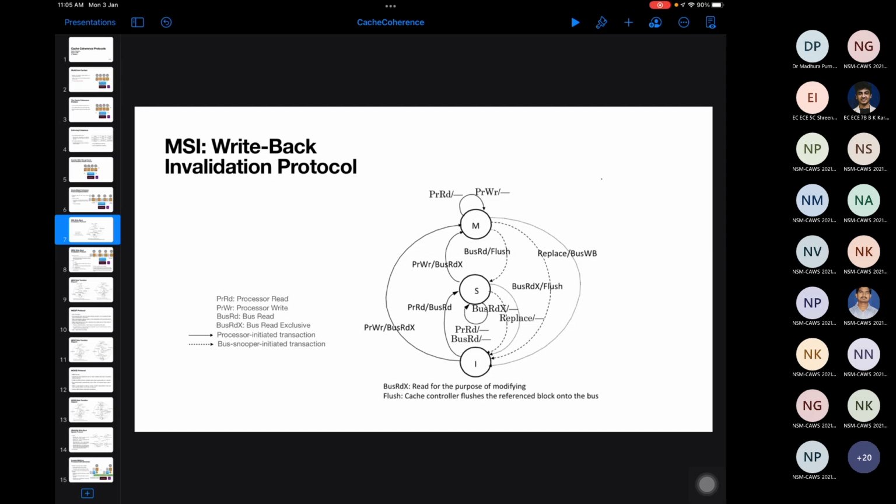Then only the performance is going to come in, right? So that's the reason why, even if there is an overhead, they have to use this coherency protocol. But now, when you have to use a coherency protocol, why can't we optimize it? Try to reduce unnecessary transactions on the bus, so that the bus will be utilized efficiently for useful operations.